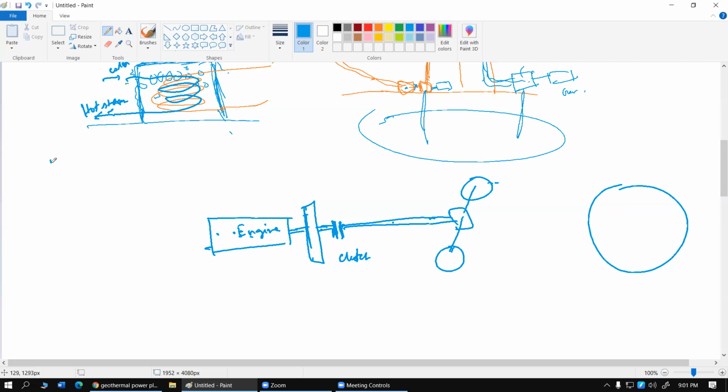So let's say if I try to show you with respect to time, this is the power output and this is the time scale of a single cylinder IC engine. Though it works in the intake duration, it will not provide any power. In the compression stage, it will not take any power. Particularly in these two places, it might actually also absorb power. For example, in the compression stage, it will absorb power from the flywheel.